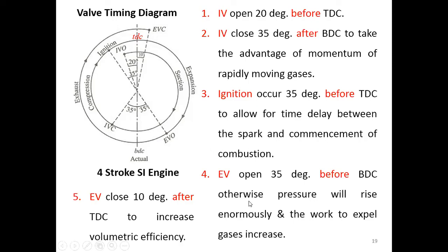So that we can reduce the magnitude of the pressure, right? Okay, and we also need the work to expel the gas, right? Because in here we still have high pressure above the atmospheric pressure, right? So we make use of this pressure to expel or discharge the exhaust gas out from the cylinder by letting the exhaust valve open first.